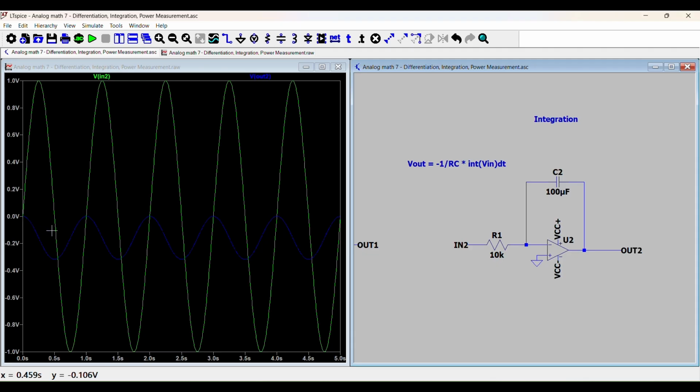The reason why the amplitude is decreased is because this is not actually sine of t. Sine of t has a period of 2 pi seconds, my bad. And so this is much smaller than sine of t. So when we integrate it, there's a sine wt factor, and w gets divided after you integrate. And the larger the w, the smaller the output.